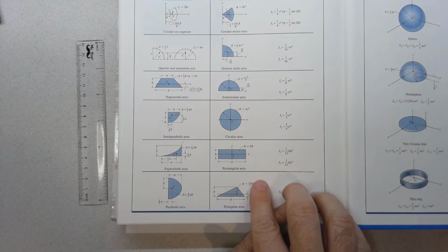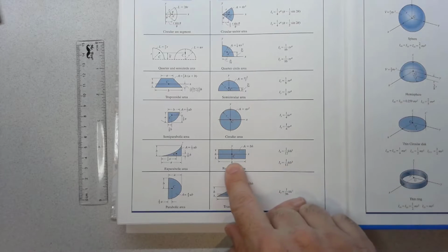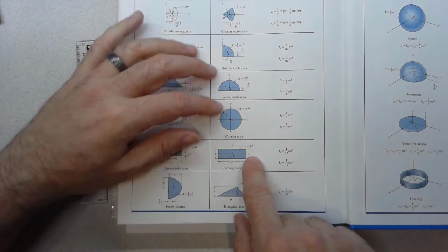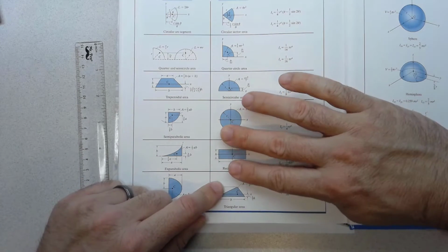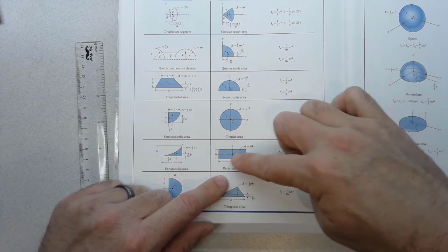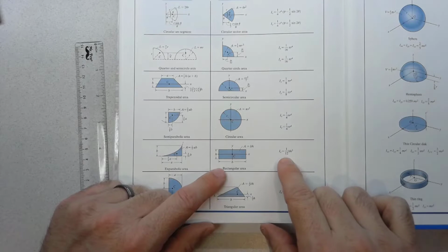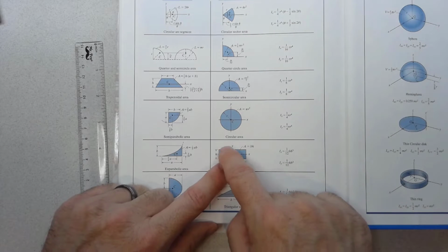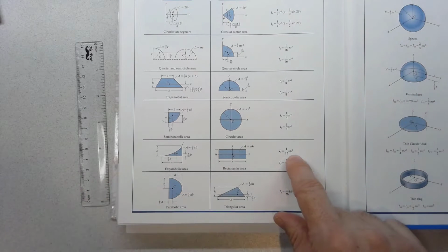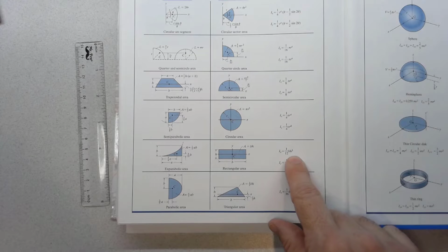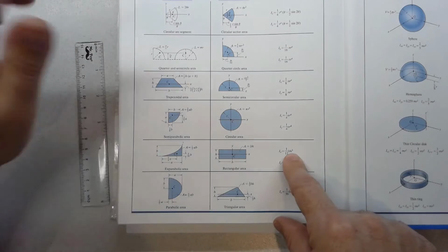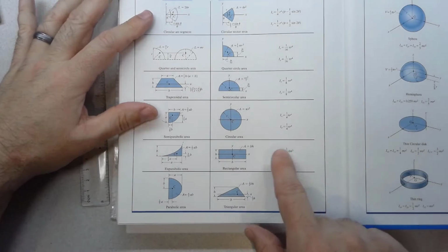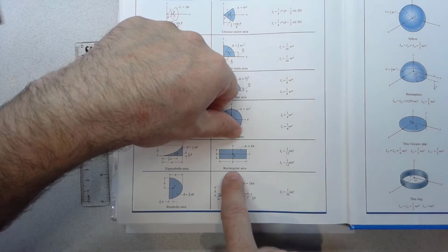So the most common one we'll work with is rectangles, and so the moment of inertia about the x-axis, so that's about, if we look at the shape relative to this axis here, is 1/12 base, so the width, times the height cubed. And that cubed factor is an important concept in beams: there's a much greater impact on the stiffness of a beam the further away from the axis you're bending you get.